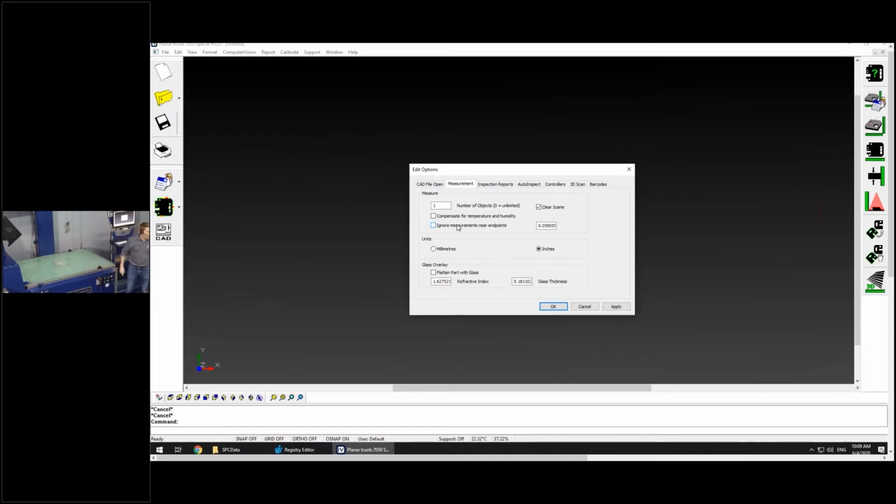So let's say, when you guys cut parts in the laser, a lot of times what will happen is these will be 90-degree cuts. The laser is still going to round off just a little bit of an average around that radius. Now we measure that and we round it off even more. We've got compound rounding going on, and then your part sometimes fails in the corners and it drives people nuts.